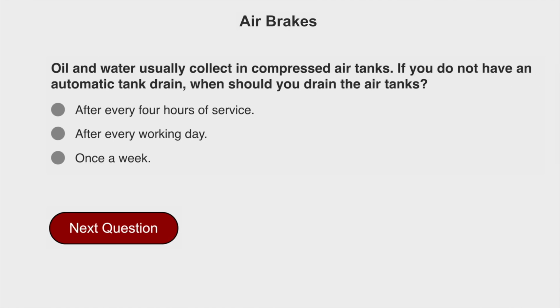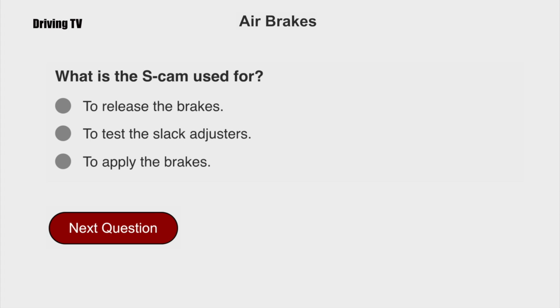Air Brakes exam number 1. Oil and water usually collects in compressed air tanks. If you do not have an automatic tank drain, when should you drain the air tanks? After every working day. What is the S-cam used for? To apply the brakes.